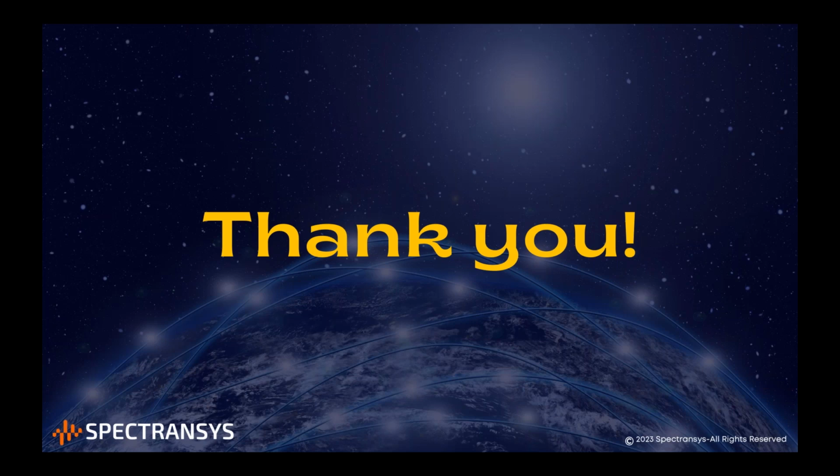And a little design knowledge, a little engineering knowledge, maintenance knowledge, operation knowledge, all these things are very essential, because your spectrum alone is not going to tell you. It tells you where the problem is. But in order to really identify and segregate the source of the problem and relate it to these various behaviors, you need to consider all these parameters. Of course, every time they may not be required. Sometimes the vibration data directly will be able to help you resolve the problem. But sometimes, depending on the behavior and the response of the machine, you may need to correlate to the various process parameters and other operating conditions also.